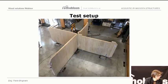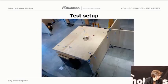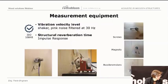And here an example of an X junction, so the connection between 4 walls. And here a configuration in which we tested the performance of the slab. For the measurement, we used the shaker and the pink noise filter. And actually, we used different types of shakers in order to have results that will not be affected by the type of instrument. Of course, all the measurements were carried out in accordance with ISO 10848.